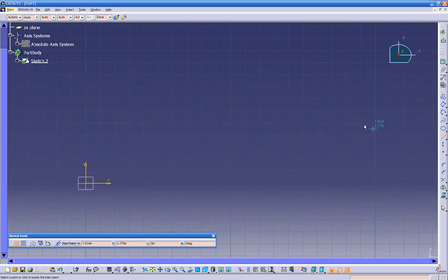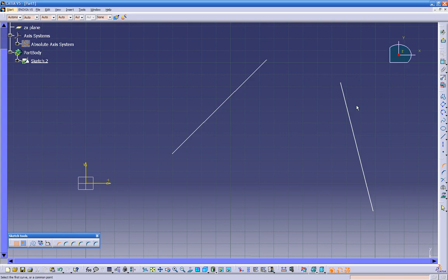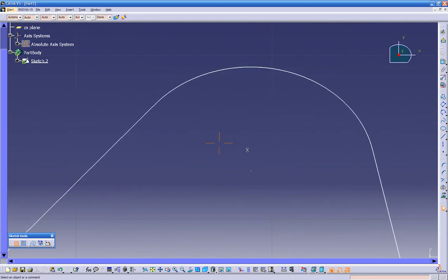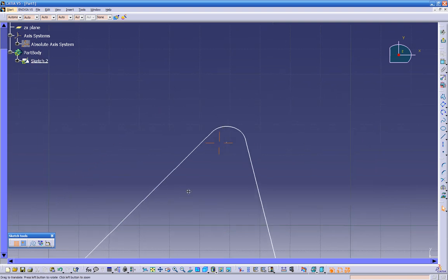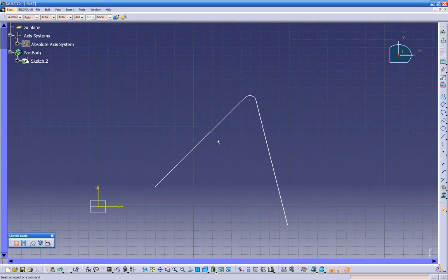So pretty much, let's try one more time. Create another line, and let's click escape, get out of here. Let's go to corner radius. Let's pick line number 1, line number 2, and before we snap it into place, let's click the tab key, and let's type in the dimension over here, 1/4 inch. And as we zoom in here, we can tell we have a perfect tangency between this line and this arc. So that looks pretty good. I like this option better.